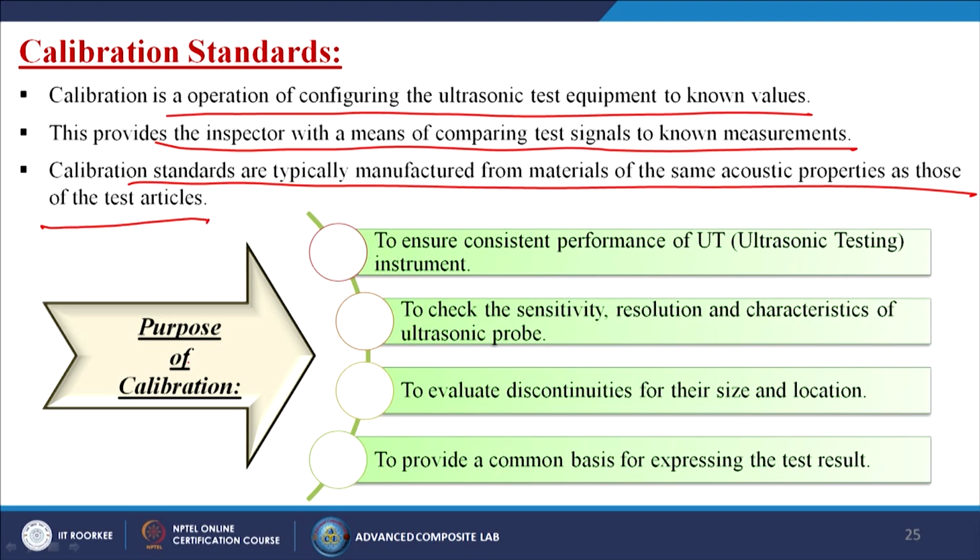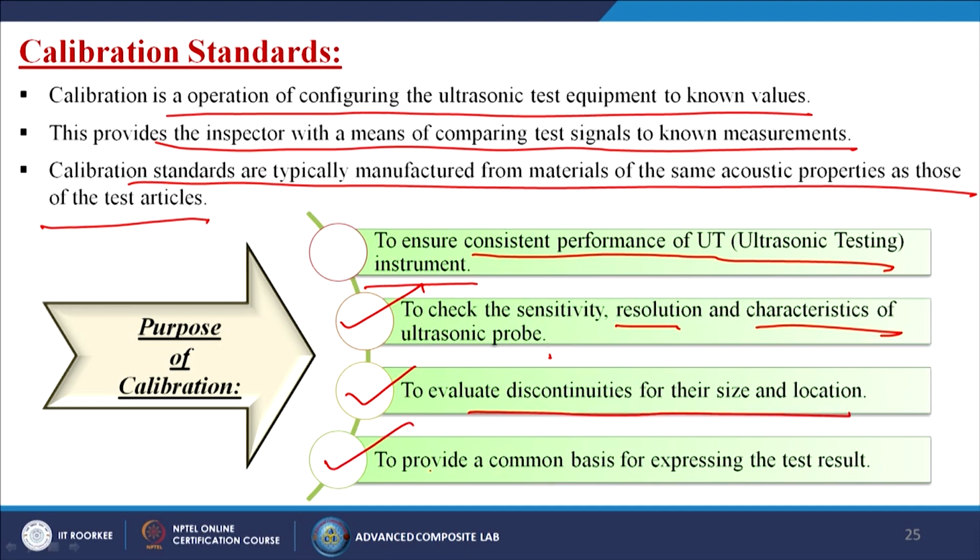Purpose of the calibration: to ensure consistent performance of the ultrasonic testing instrument, to check the sensitivity, resolution and characteristics of the ultrasonic probe, to evaluate the discontinuities for their size and location, and to provide a common basis for expressing the test result.